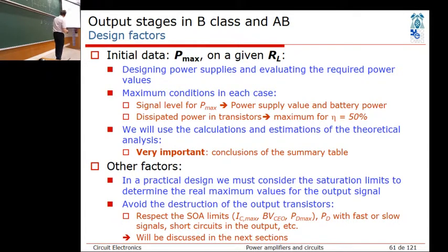And that's actually one reason why on audio amplifiers, although this is ugly since it does bad things to your signal, you usually bias it to 0 and then have a high pass filter at low signal, say cutoff frequency at less than 20 hertz. So that's what you do for audio amplifiers. You never DC couple an audio amplifier, otherwise you end up killing the amplifier if you have a DC signal coming in.